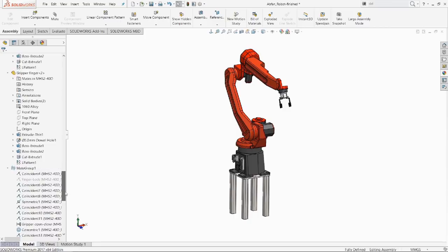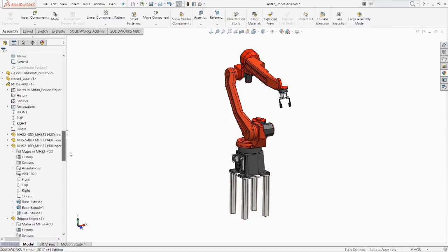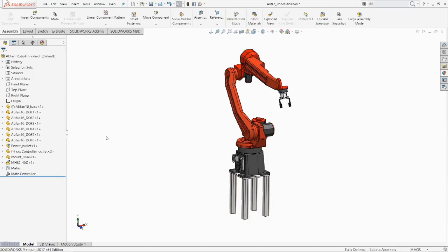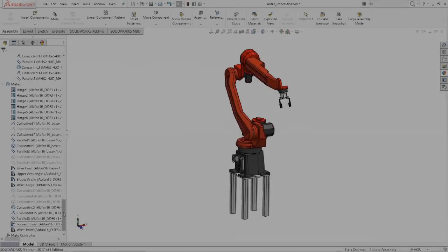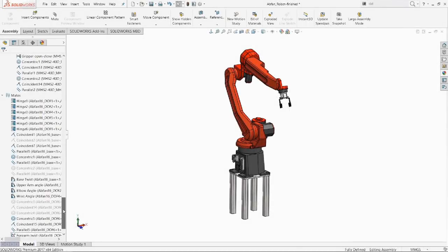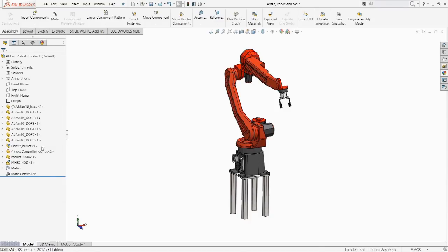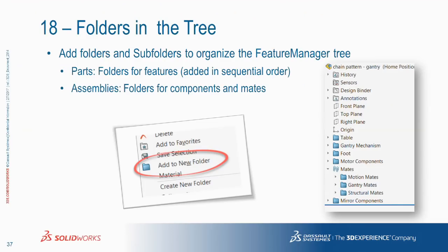Here I am all the way down here. This subassembly, the mates are expanded. Here's this part that's expanded. All this stuff's going on here. All I need to do is hit Shift and C, and the tree gets collapsed. So I can start fresh. But anywhere you see collapse items, it doesn't matter where you are. You could do it on a mate, on a sketch, on a part. Just in the tree, right-click and hit Collapse Items, and that's what that will do.